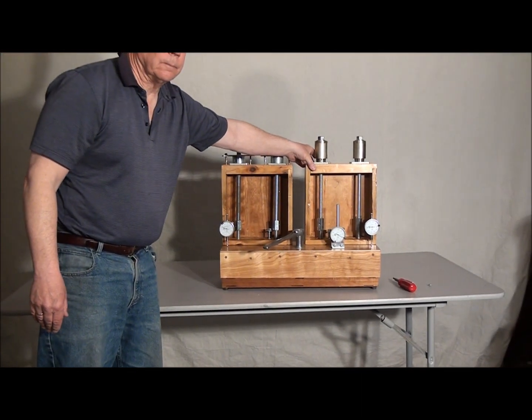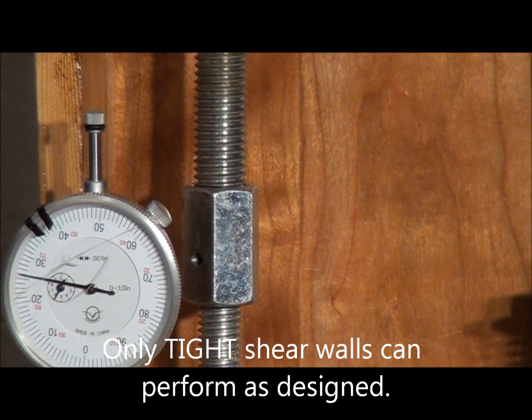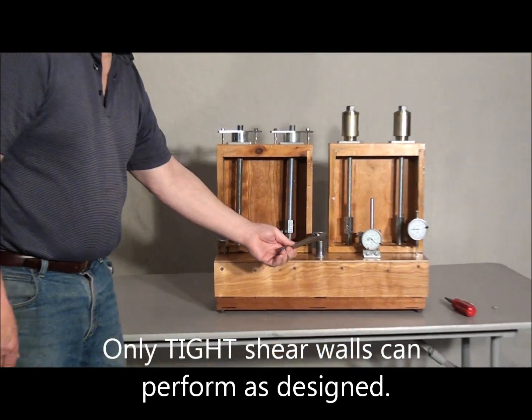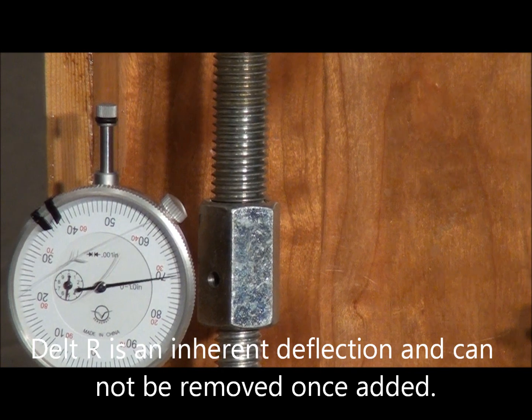It's an inherent part of the design. It cannot be removed. The ratchets have to do this in order to, in this case, go down the rod and make up for that shrinkage. Only a tight system can perform as designed. Because delta R is inherent, it cannot be removed, and it will create a looser shear wall.